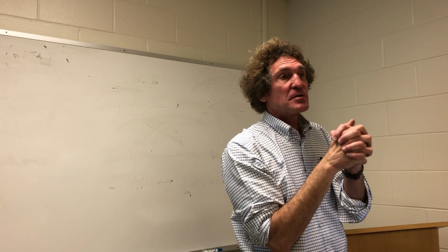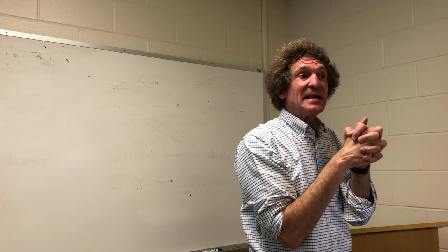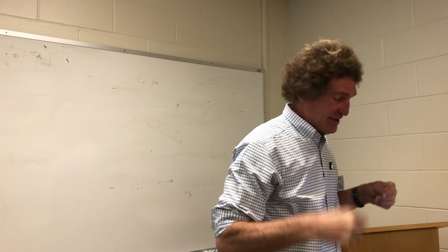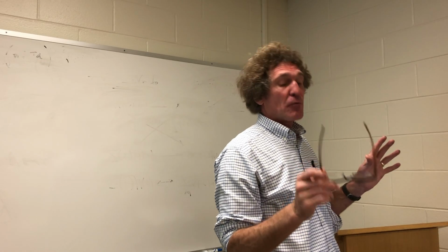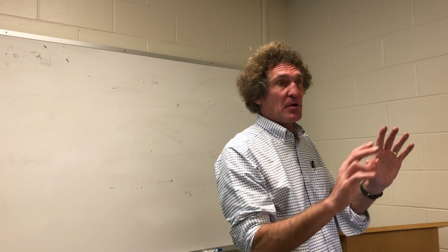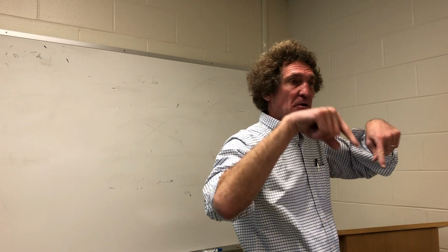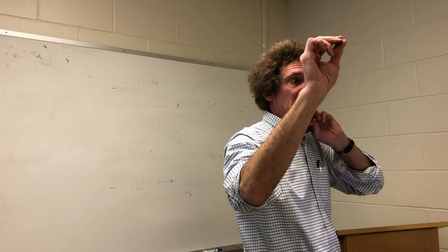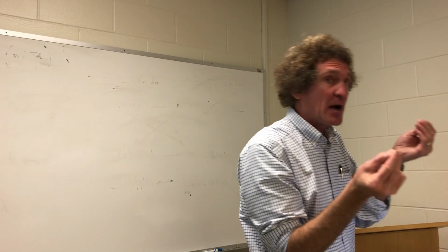There's distortion that Doppler shift undergoes. There's distortion that ranging gets, and there's all sorts of ways to mitigate that, and that's some of the fun stuff coming up. But you have to be aware that when you get a radar picture, you're not looking at time domain. The thing that's rendered to you is something in 2D usually, where targets are. Sometimes 3D. Not just where the target is, but its velocity.